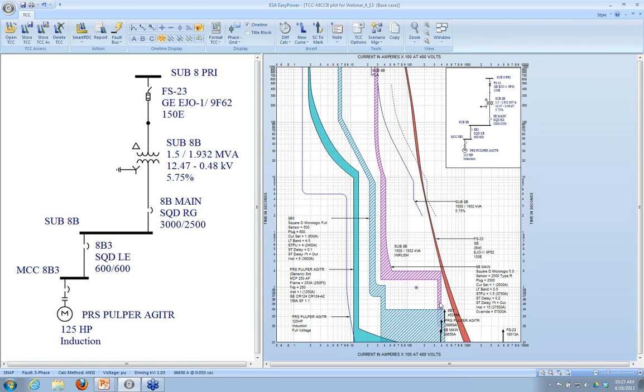So why does this stop here? Why is this so narrow? It's because it's hitting the maximum fault current. We're going to talk about TCC clipping in a minute, and maybe that'll make this more understandable. But basically, this is as high as I can set it. So I'm still going to have a small region here where these two will not coordinate. But by setting this as high as possible, I improve my odds, because these are maximum fault currents out here. A lot of my faults, particularly arcing faults, are going to be a lower fault magnitude. So for those, these are going to coordinate.